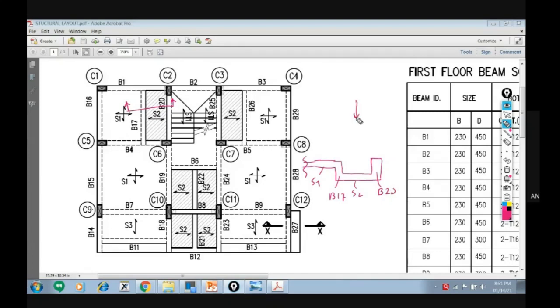Now if you look from above, these two lines are visible clearly, so B20 is clear. Now actually this is wrong. I think this drawing is wrong. It should be thick. See, many times engineers and draftsmen make mistakes like this. This is a thick line, yes or no? Because the staircase is open. Do you agree? It should be a very thick line, right? Yes, like this.